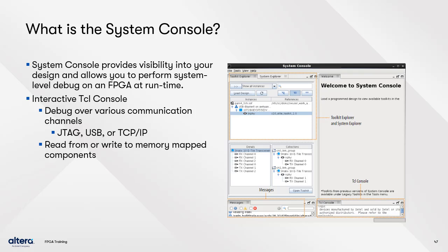The Tools pane allows launching tools that use the System Console framework or to enable GUI widgets created by your script. The Tcl Console pane allows running commands and Tcl scripts from within the System Console. You can also source Tcl scripts. Finally, the Messages pane displays messages generated when running tools within the System Console.